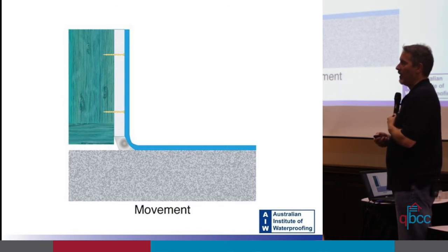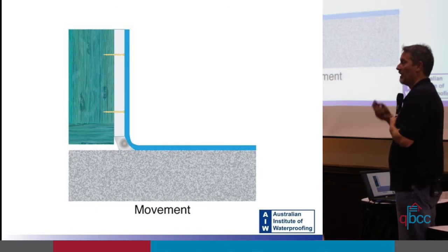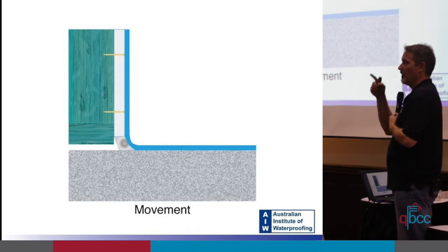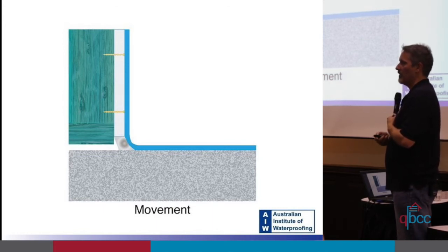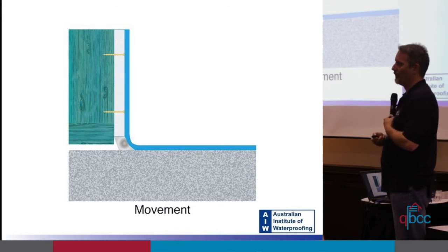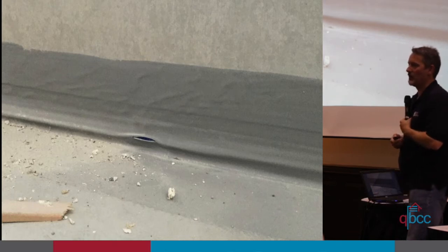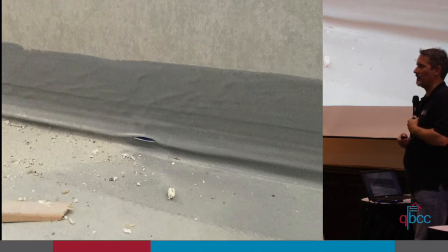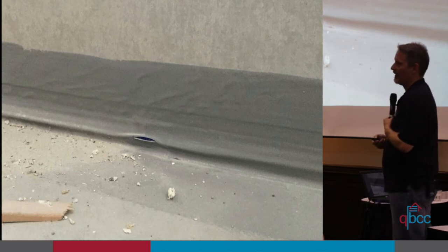Right? The ideal way, so you have no issues or less likely even than that to have issues, is to use the joint tape with a rubber embedded inside the fabric. Do the detailing with that. Then you can eliminate the bond breaker, it'll do the same job. And what you can't do is put masking tape in that transition. You will just about always get that.